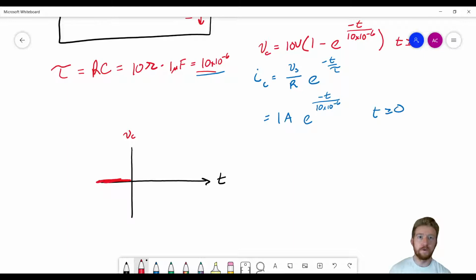Well, a capacitor won't change its voltage instantly, so we're going to see a slow ramp up in that capacitor because that resistor is going to prevent current from flowing into it, so that resistor is going to dictate how slow it is. So we're going to see kind of a ramp up like this, and after a while, it's just going to flatten out. Because after a while, it pretty much gets to where it's fully charged, and it's just going to get closer and closer to a certain value.